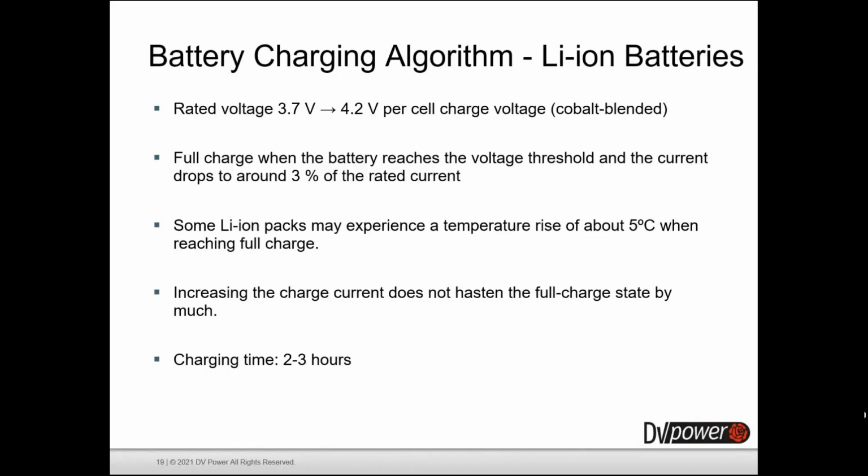So lithium-ions with traditional cathode materials of cobalt, nickel, manganese, and aluminum typically charge to 4.2 volts per cell. The tolerance is plus/minus 50 millivolts per cell. Some nickel-based varieties charge to 4.1 volts per cell, and the high-capacity lithium-ion may go to 4.3 volts per cell, and even higher. Boosting the voltage increases the capacity, but going beyond specifications, so going above that, stresses the battery and compromises safety, because you can set them on fire, as I already said.